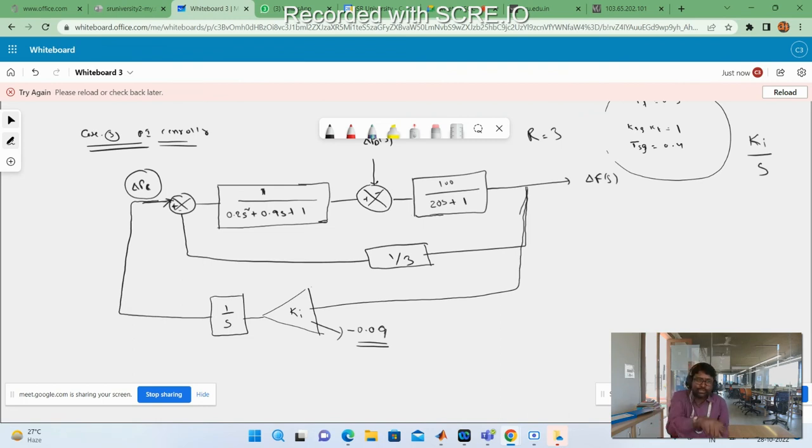Because until delta f equal to 0, your speed changer will be continuously monitoring, continuously updating, continuously varying. So steady state value equal to 0. So in case of the PI control, that's what we want actually. If the delta f equal to 0, what is the system frequency under steady state condition, even though load changes? If you use the PI controller for this purpose, what will be the system frequency even though load is increasing or decreasing? Frequency deviation is 0. I am asking system frequency. 50. Nominal frequency only, right?